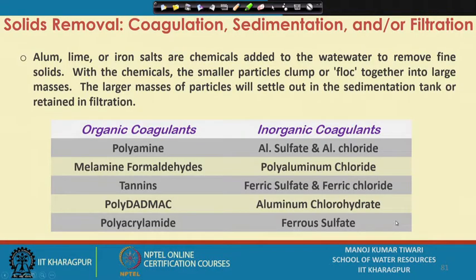That way it helps to form sweep floc, but the dosage requirements are quite high. So, there is an additional chemical footprint in adopting these coagulants for sweep floc formation at higher concentration. The organic coagulant will eventually help in the sludge generation part.